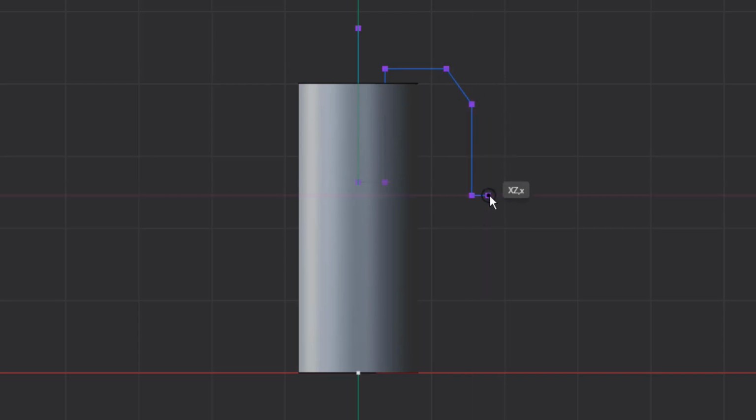So I'm going to just drag up and come down and maybe make some sort of handle here. And one thing that we want to do is look at snaps. What I mean by snaps is you can see currently it says parallel Z, which is telling me that my line is vertical and it's parallel to the Z axis. But if I want to get it horizontal to this point, I need to hover over it, hit and release Shift, and then you can see that we're getting some indication of what those marks are. And now we have our intersection point.